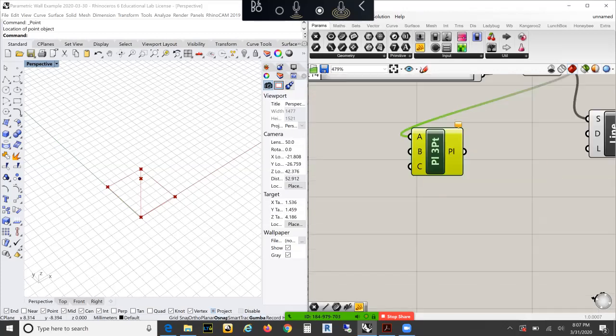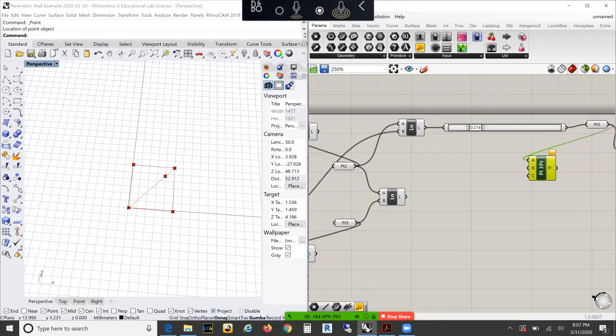So then it's asking, you have the origin, what's the X direction? Well, we're going to say the X direction is point 2. Then it's asking us, what's the Y direction, or the orientation point? Well, we're going to put that at point 3. It's almost like physics class. You have the right hand rule. You have X, Y, and now you have Z going up.